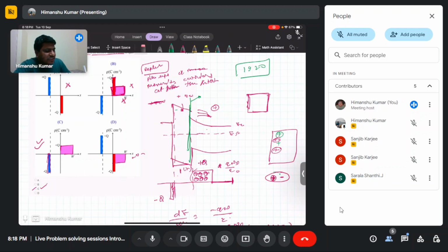This became better after the discovery of the BJT, when people started exploring silicon BJTs and those things, and then thermally grown silicon oxide became popular. It has very pristine quality and very few oxide charges. If your silicon quality is better, then your thermally grown oxide is also of very high quality. Once people got very good oxide material and interface, they started seeing a boom in MOSFET or FET technology.